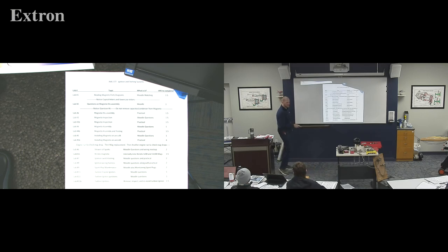Ignition switch testing, you're basically gonna use one of these boxes, go out to an aircraft. If the key is in the off position, and I'm installed correctly, should my lights be on or off? On means our switch is open between them. What our key does is it grounds our magneto out. So what you're gonna do is wire the box to the airplane, and the trick with that is you've got to disconnect the P lead because it grounds stuff out. So you're gonna be disconnecting the P lead from the magneto, I believe is how the lab is written.